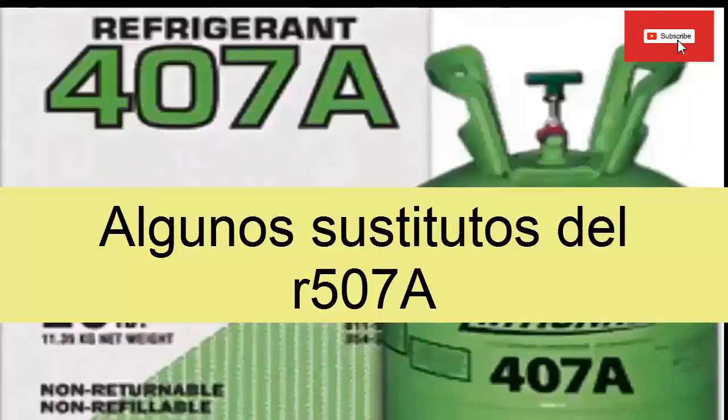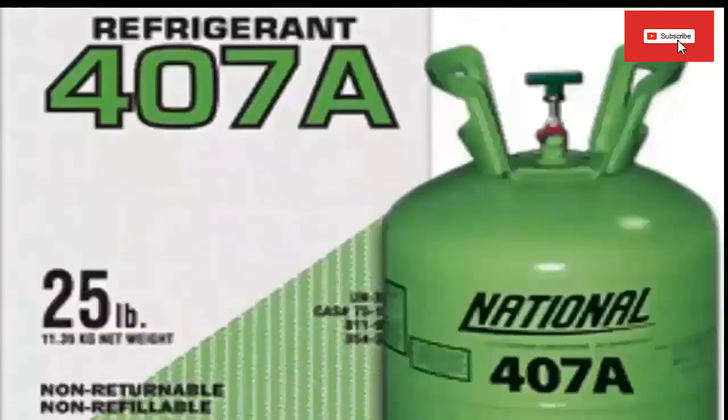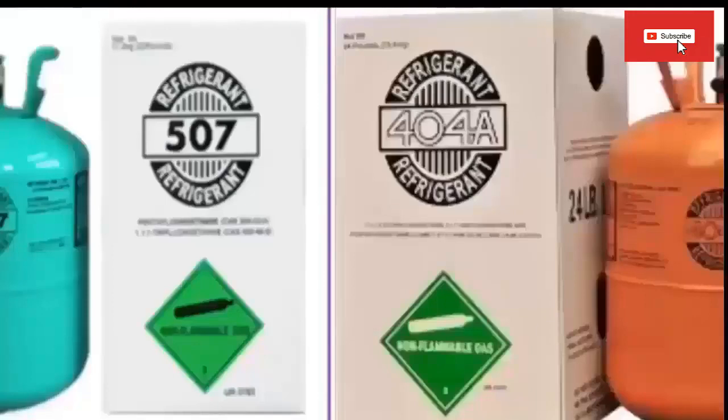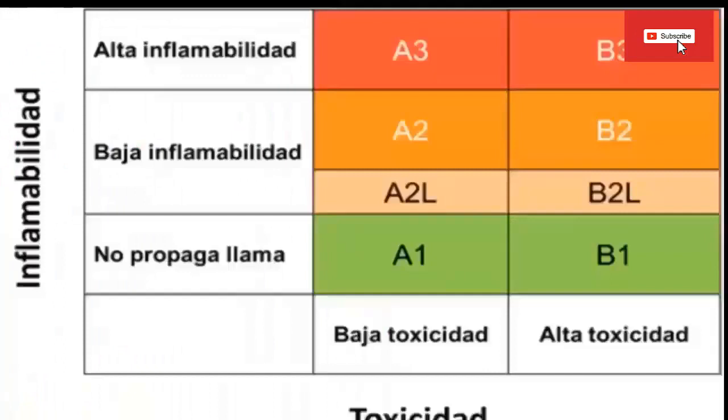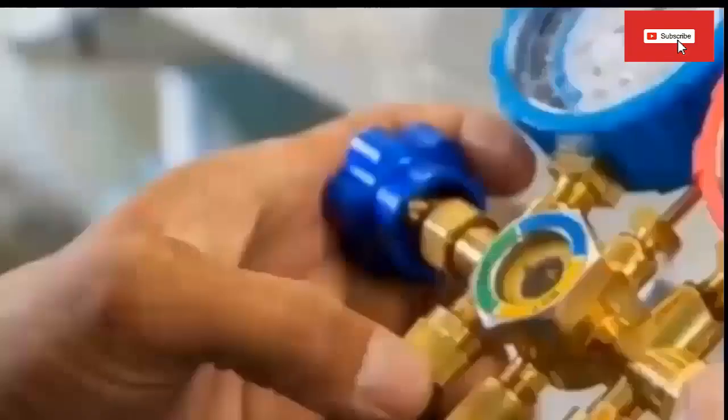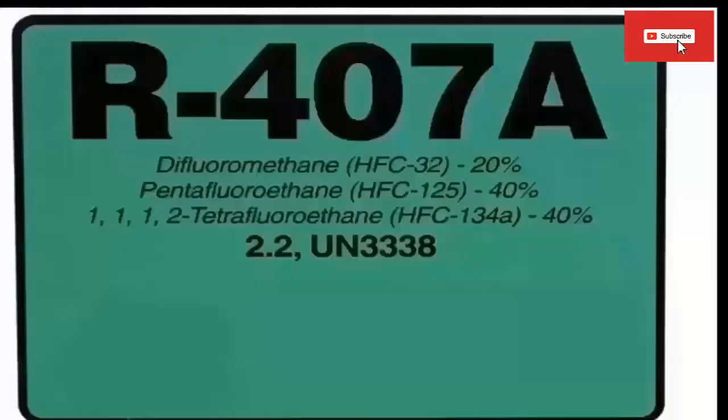R407A has been designed as a replacement for R22 gas and also as an alternative to R404A and R507A. R407A has the advantage of not being flammable or toxic, and its use as a replacement for other gases in old equipment requires few or no changes to the system. Of course, the modification of some characteristic of the equipment that is working, when using R407A as a replacement, will depend mainly on the refrigerant gas that is being replaced.